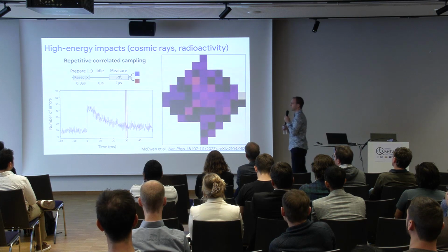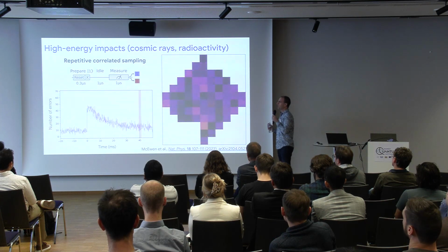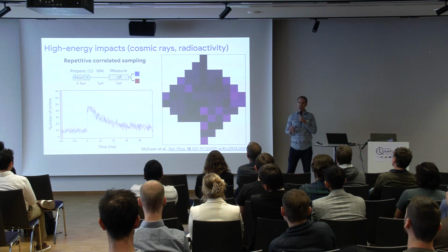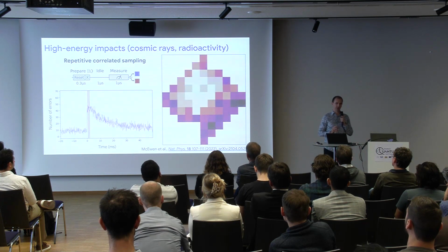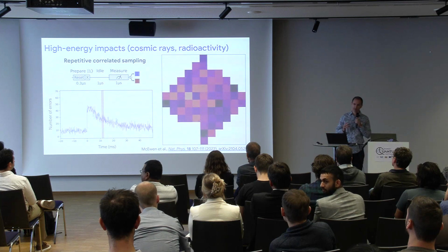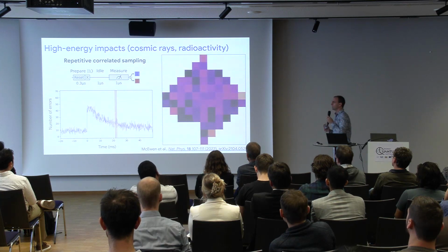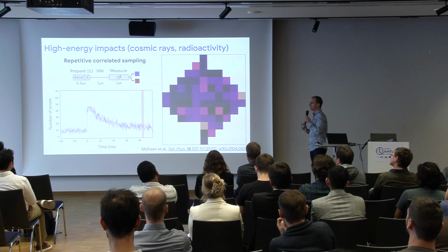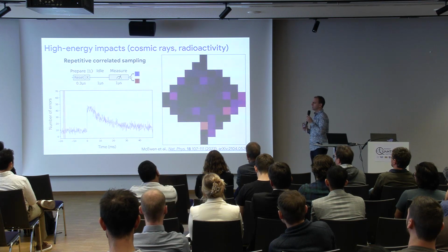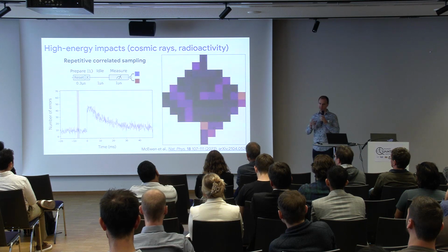So when a cosmic ray hits a superconducting chip that's operating at 10 millikelvin, it dumps so much energy on that chip that the entire chip stops working for tens of milliseconds. That is thousands of rounds of error correction. That is thoroughly unrecoverable. So, we're working on engineering solutions for this. This is an example of a correlated error that error correction has precisely zero hope of fixing.